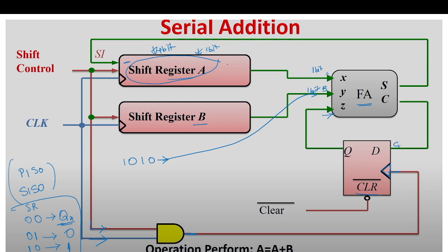For us, we have a block where we get an input, say completely this 100, but we want the output 1 by 1, because it's 1 bit. We want the output to be 0 for the first clock cycle, next clock cycle 1, next clock cycle 0, next clock cycle 1. And this can be obtained only if we use a D flip flop.